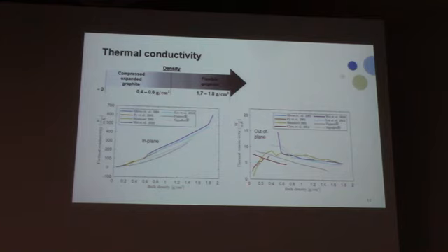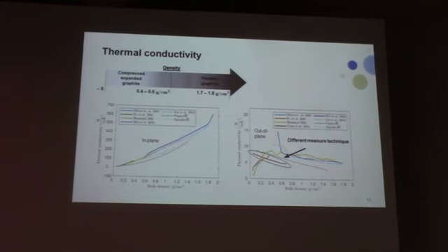Here we can see that the thermal conductivity in the through plane at the beginning increases, because at this stage the material is still not interlocked. So together with the interlocking, the conductivity increases and then decreases, because the deformation unit tends to be orientated more in the in-plane direction. There is only one set of data which seems to be a bit out of the trend, but maybe because of a different measurement technique, and actually it is one of the newest, from 2014.